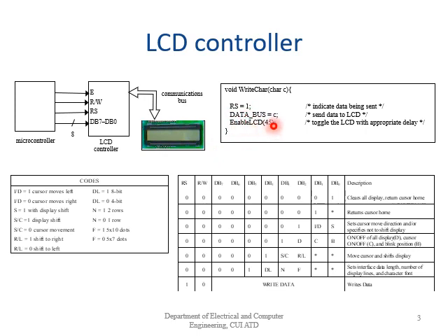So that was about the LCD. We can initialize our LCD by using these control words, and once it is initialized, we can write data, and for anything to be done we must toggle the enable bit. So that was about the LCD controller, its control words, codes, and finally a simple code for writing something on the LCD. So let's move to the next slide.